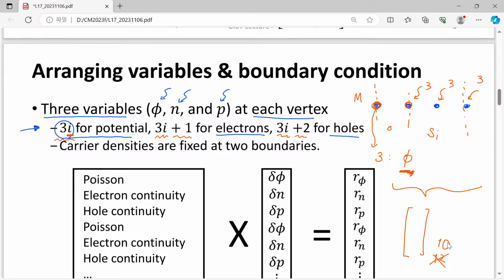If we have only silicon variables or semiconductor materials, then this kind of approach is quite accessible. However, if we have different materials, especially oxide or nitride, where such insulating material is involved, then this number 3 based indexing system will fail.